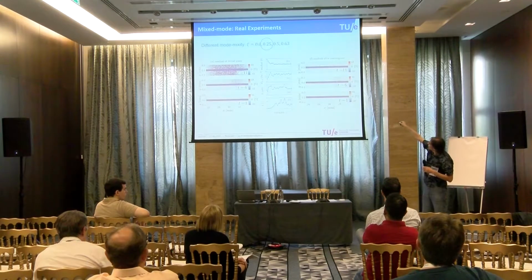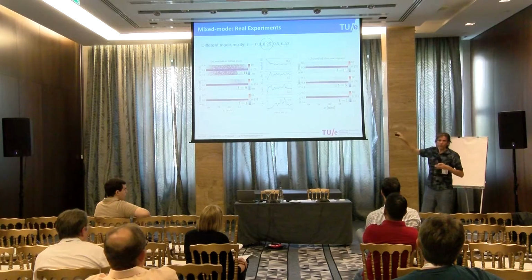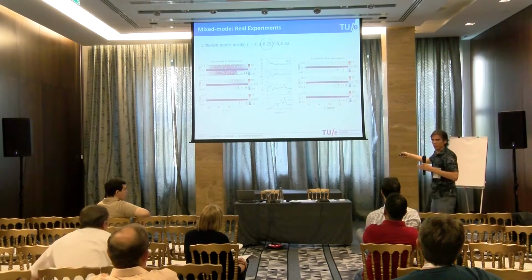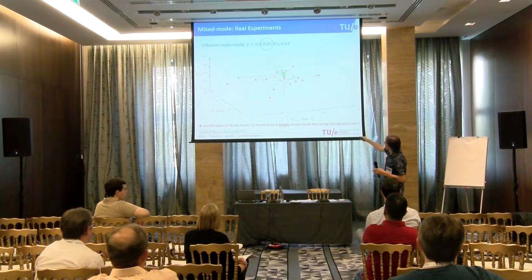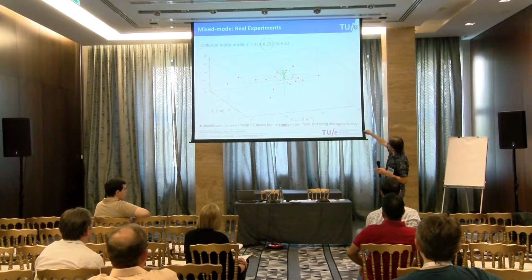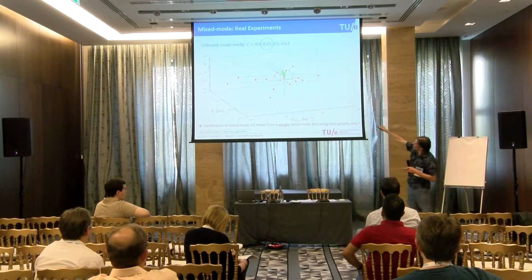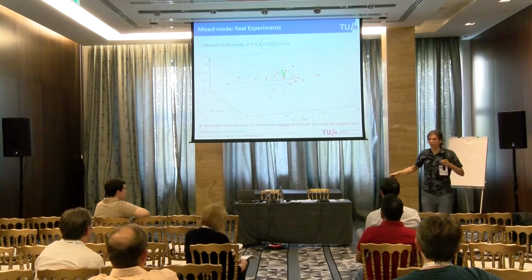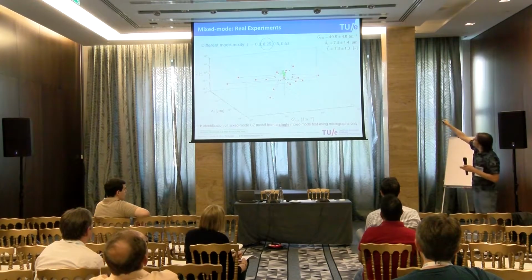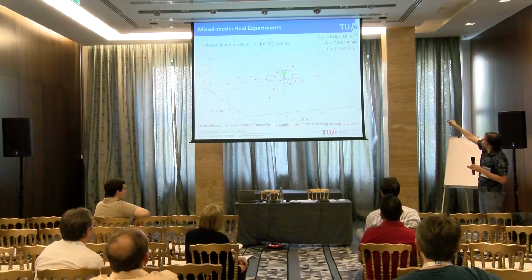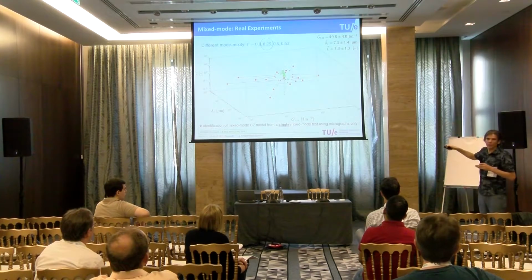So this means that the interface model is doing something correct. It's describing it quite close. And so we can have identification here, and if you now have different initial guesses, it does converge. There is some variability, but it converges. So let's look at these numbers. So we get these numbers. This is the mode 1 fracture toughness, mode 1 critical displacement, and the mode mixity parameter.